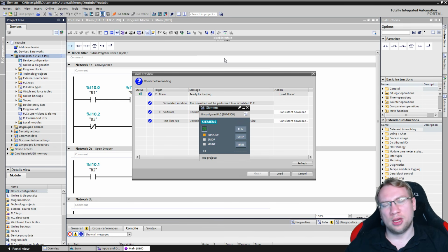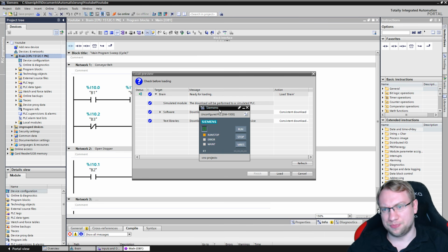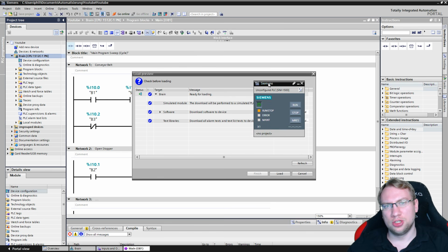It could be that you have a pop-up message right now saying something like, hey, simulation is turned off for your PLC. So you have to turn it on. There's an OK button and you turn it on. It just tells you that you are turning on simulation for this PLC, which could be unsafe in some cases. But for now, for beginners level, it's totally fine to turn it on. So hitting OK on the pop-up that's there. And this simulation here will open.